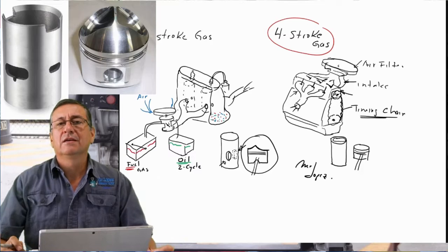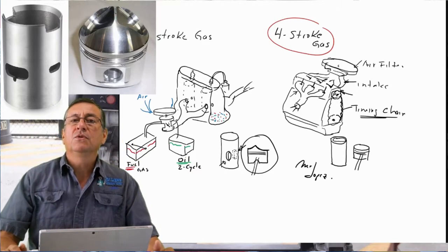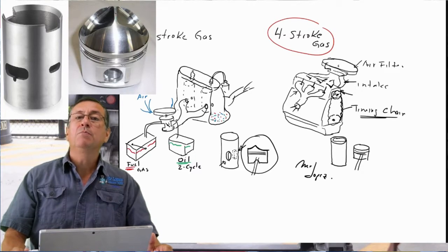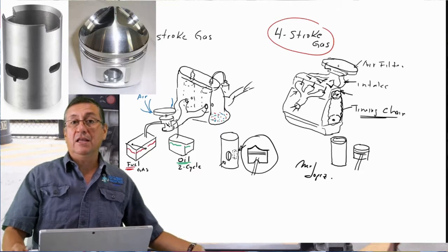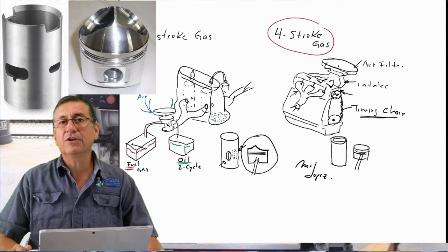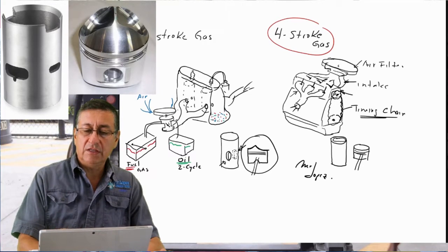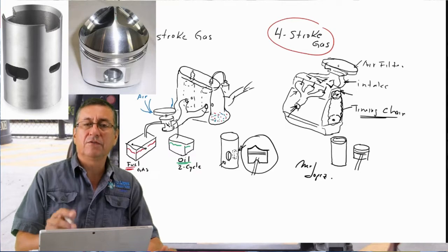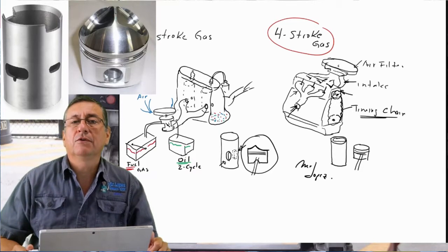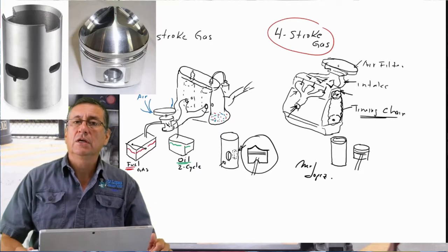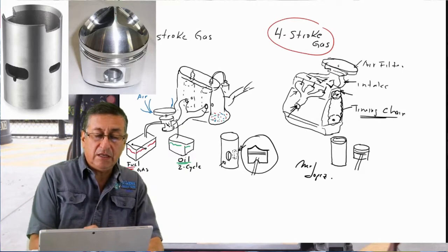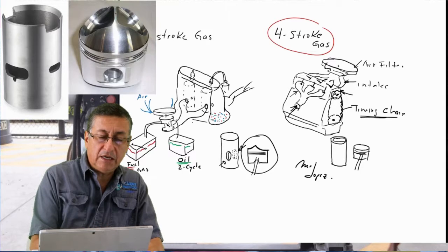One of the differences, if you check by visual inspection: the 2-stroke engines have the input of the mixture and the output of the gases in the bottom of the block, not on top. In 4-stroke engines, the intake and the exhaust manifolds are located on the head, on each side of the head, like the picture that you have on the screen right now. This is 4-stroke. In 2-stroke it is in the bottom of the block, because in this particular case, this is the intake manifold.